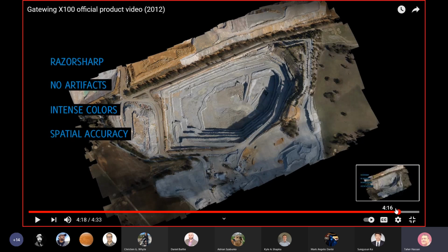My question for you is, before drones, how did we use to find the XYZ on a mine? The answer obviously would be either total station or GPS. Now, with GPS, especially for this application, is it easy or difficult? What is the danger? What is the problem here with this application? You'll have to physically go to every individual part of the mine, and some parts of the mine may not be the most accessible on foot.